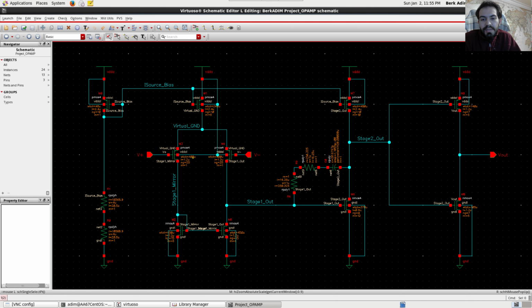But we are using a PMOS input stage because we want our DAC output to accept common mode inputs as low as 0, and well, it cannot accept as high as the supply voltage, but it actually can accept 4 volts. We are using a 5 volt supply here. It can work in 4 volts, so we actually have a wide input common mode range.